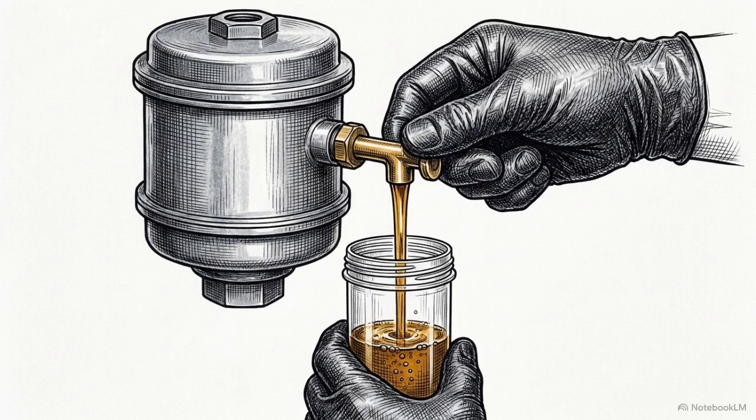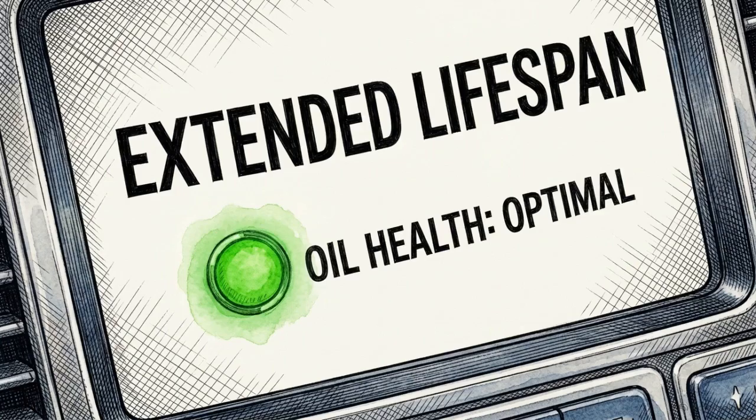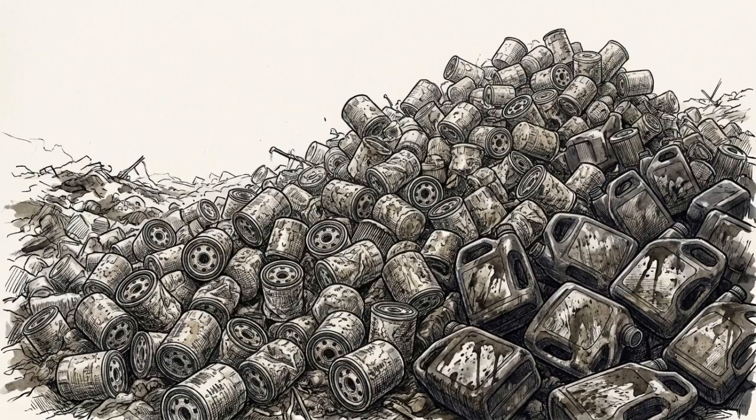Our duplex filter system provides a built-in solution for this by using the offline chamber as a pressurized sampling port. Periodic laboratory analysis of these samples tracks the remaining additive levels and viscosity, providing a precise data point for when the oil must be replaced. Shifting to condition-based data allows high-quality synthetic fluids to safely run for 50,000 miles or more, far beyond traditional estimates. This continuous loop system reveals the staggering amount of waste built into standard maintenance cycles.